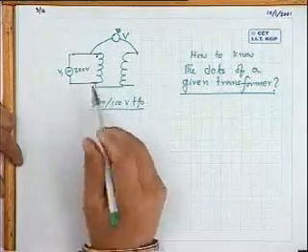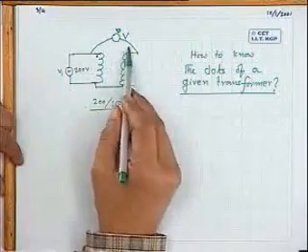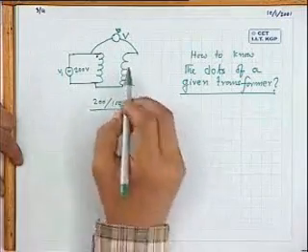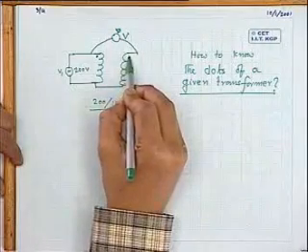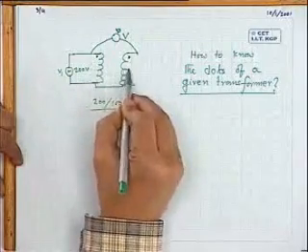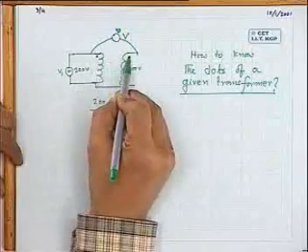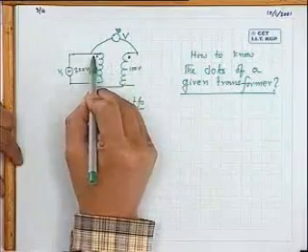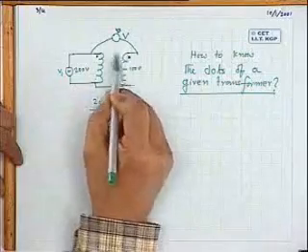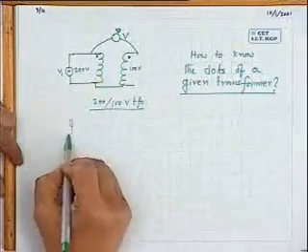Now suppose these two points are joined. Then this voltmeter reading will be this voltage and this voltage. It will come like this. Now, if this is also suppose dot, I do not know which one is dot. Suppose this is dot. Then you have applied 200 here. Here the RMS voltage will be 100 volt, no doubt. This dot, if it is suppose like this, then that means you start from one plus, then this is minus, and once again minus plus. So the difference will be read by the voltmeter.